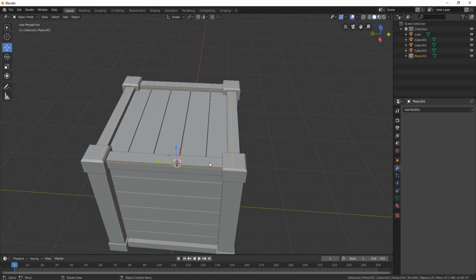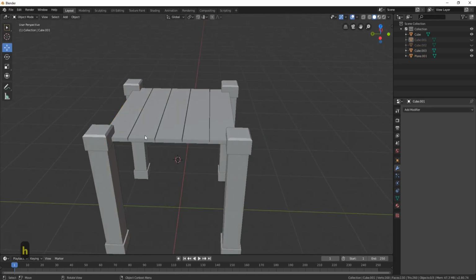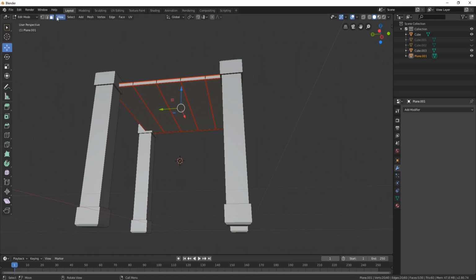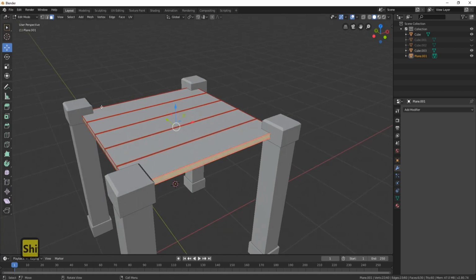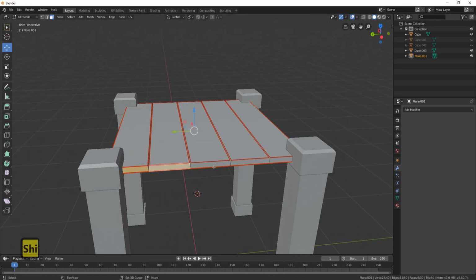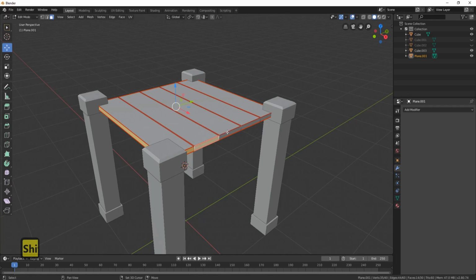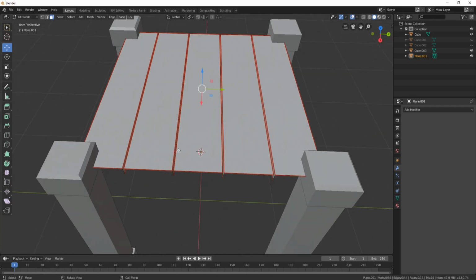Now before we add our mirror modifier, let's just clean these up a little bit, because we have got things that we don't need. So let's click on this, go into it, and we're going to hit the face select the bottom faces like so. And we don't need the bottom faces, no one's going to see in it. We don't need these edges here, no one's going to see into that, and we certainly don't need these ones here either. So on both sides of these, let's get rid of these. Click delete and faces, and now you're going to be left with something like that.